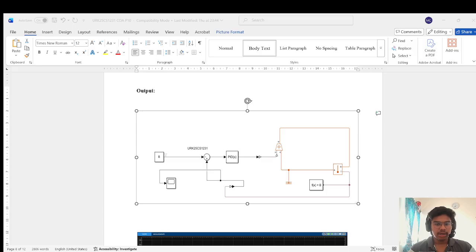The components are the controlled source, the electrical physical network, the ground, and the error block. Next is the feedback path, where the sensor output goes through the PS-Simulink converter, which then feeds back to the summation. This PS-Simulink converter converts from the physical to the digital signal.